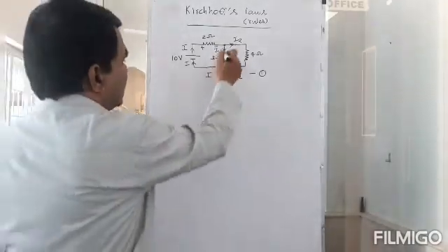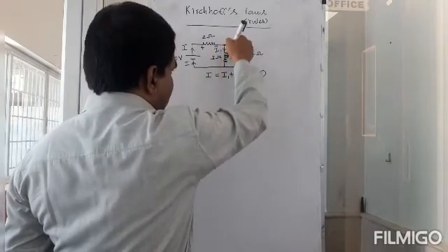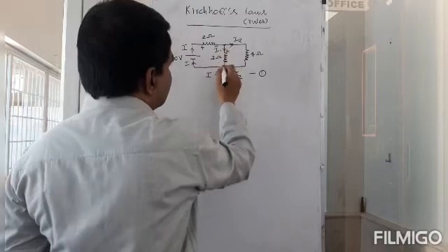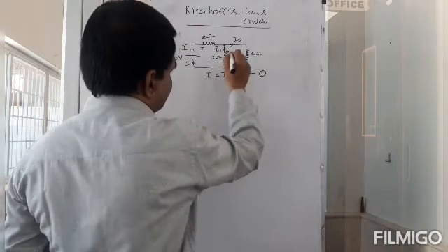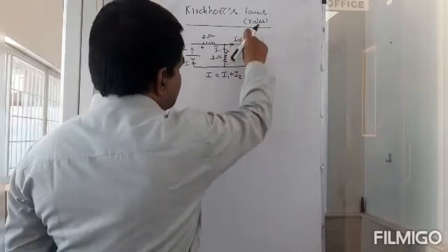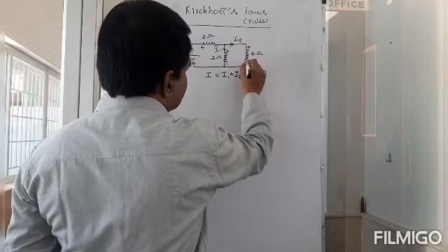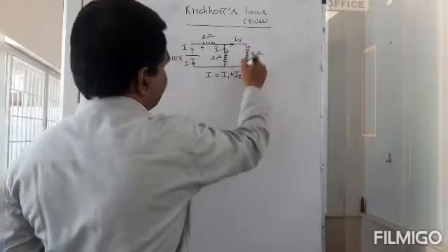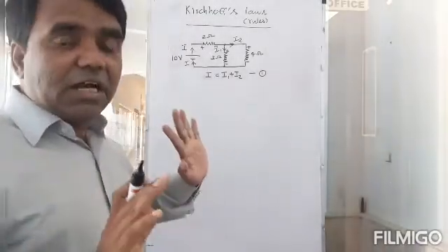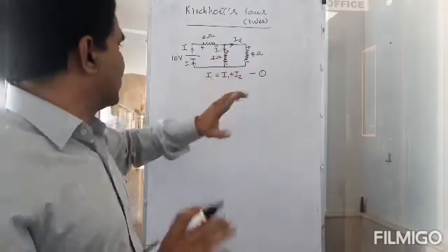I1. I will talk about this resistor. So I1 is entering this resistor here, so it is positive. Leaving the resistor here, it is negative. Okay? And then I2 is entering this resistor here, and leaving the resistor here, it's negative. So once I've chosen the directions, I cannot arbitrarily choose this is negative, this is positive, this is positive, this is negative. I can't do that.